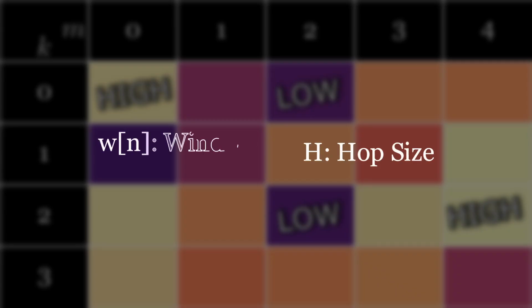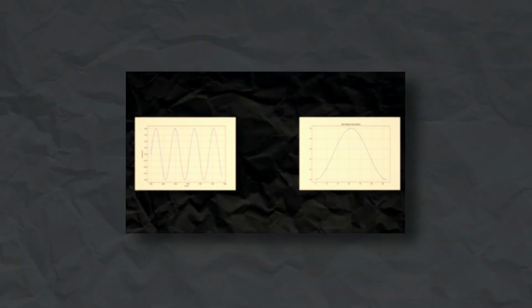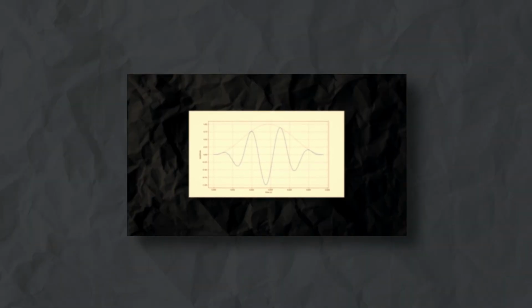Before we can get to this point though, there's still the hop length, and more importantly, the windowing function. Like I said in my granular synth video, a windowing function is something that, when applied to a signal, warps the signal to follow its area. It's used in places like statistics and other areas, but in digital signal processing, it's used to combat spectral leakage.